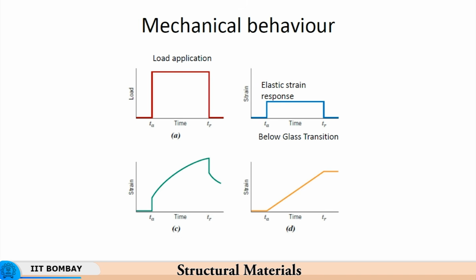So there is a phase lag or time lag between the load rising or stress change and the change in the strain. That is something which is very crucial here. And then in case of fully viscous response, you have this type of curve where strain is directly proportional to the time. So again there is a lag, but here it is a non-linear change, and here there is a linear change.